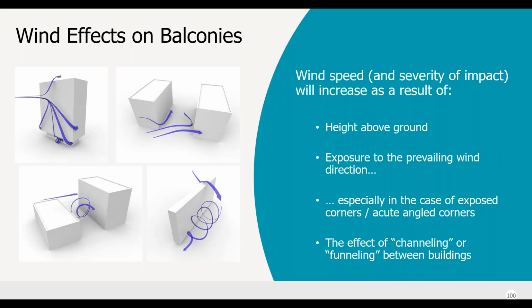Exposure to the prevailing wind direction, and especially building corners, around which you often find some of the greatest accelerations. And then also the proximity and arrangement of all the other buildings around it that give rise to all sorts of effects, which we might refer to as channeling or funneling of the winds. Often you have recirculation of wind in the wake of a building. All these are things that we should be aware of and potentially concerned about as we're designing the building. Next slide, please.